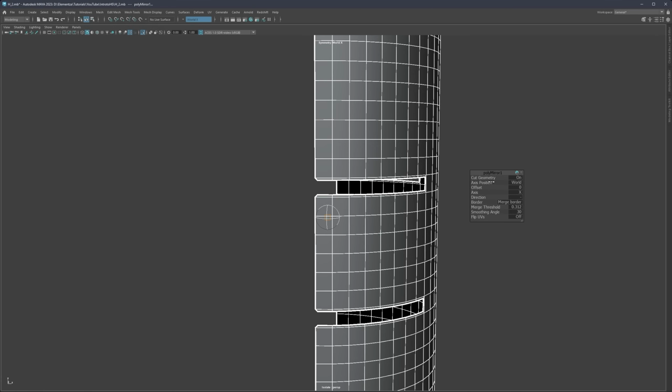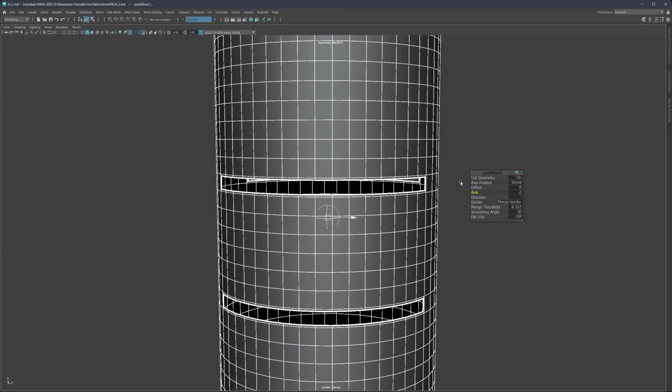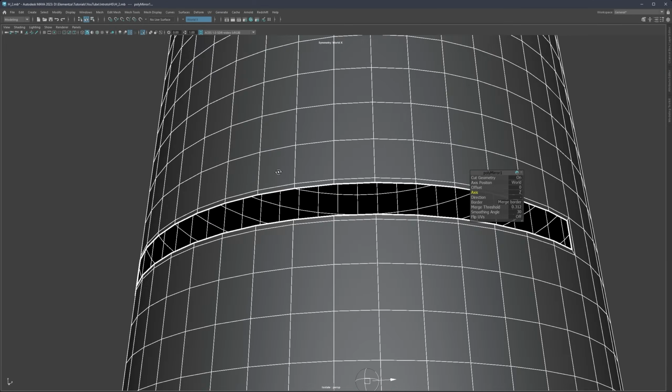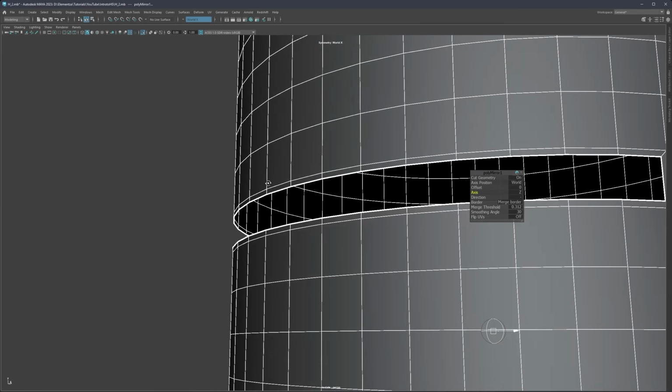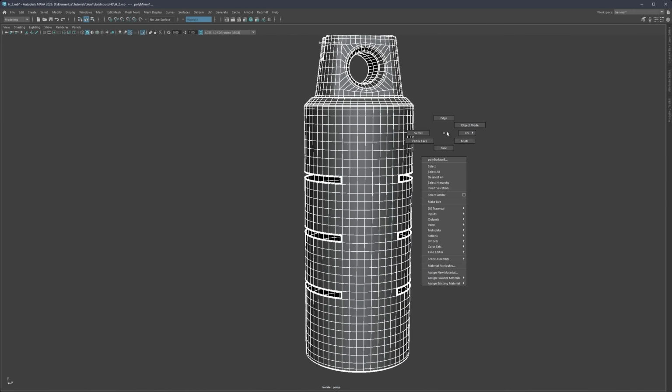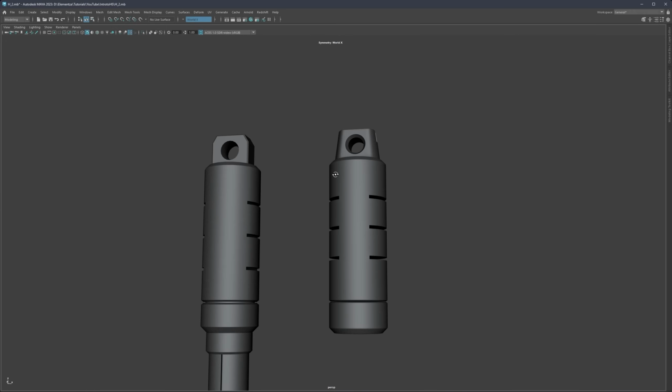And then just make sure again that the axis is set to Z, because this is going to be the axis for the mirror, and that the axis position is set to world. And since we are in the world center, that is going to be aligned. And now notice that here in the middle, everything is also going to snap. So let's just hit Q to confirm, go to object mode, and there we are.